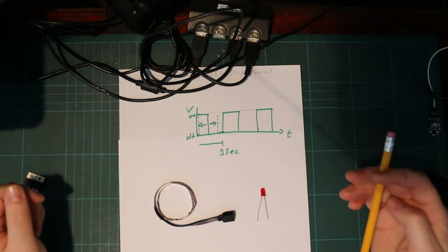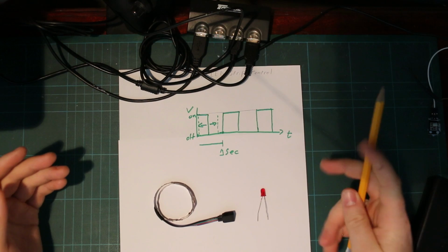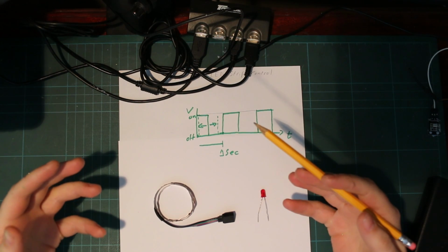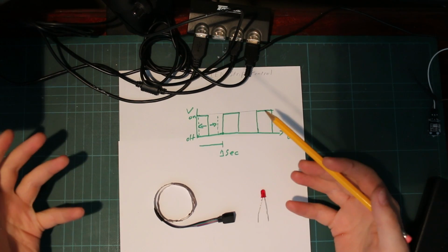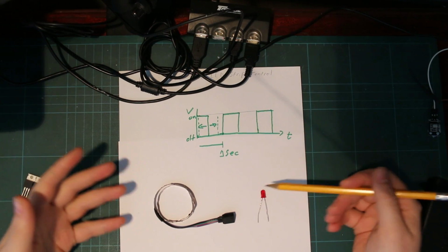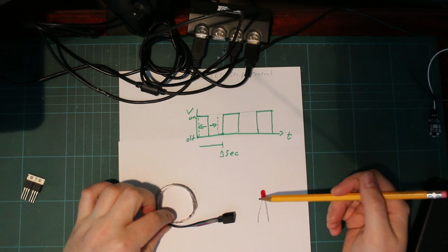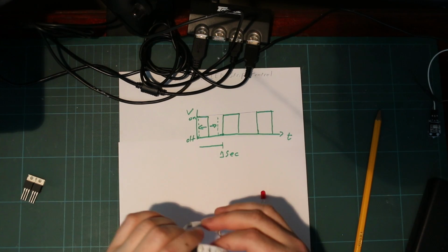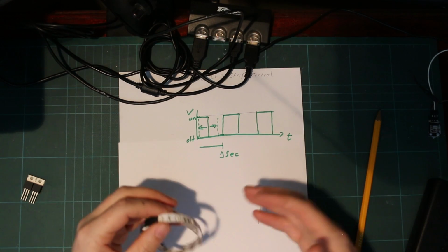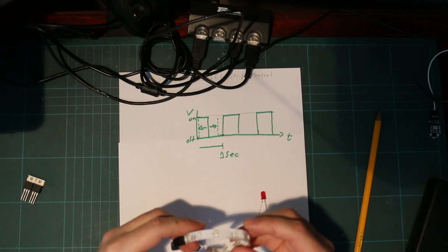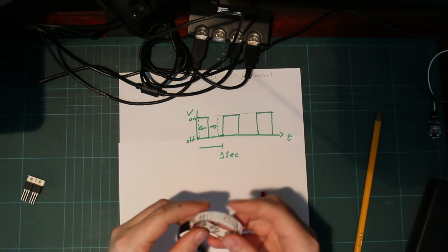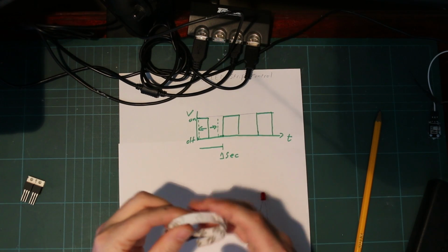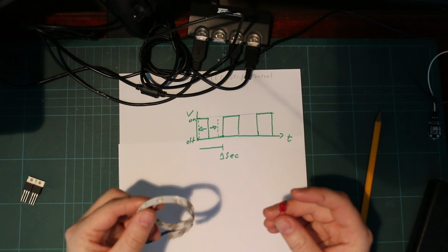So next up, I wanted to start expanding that out. So this, we're just controlling a single LED with one color. And if you want to expand that out to control multiple different LEDs with the same color, it's the exact same principle, but a few things change. So here we have what's called an LED strip. This is a very basic one. There's a few different varieties of these. This is the very basic RGB one. There are the ones that are sort of individually addressable, so you can kind of control individual LEDs. This isn't one of those. This just controls all of them at once, so it's all just multiples of this.